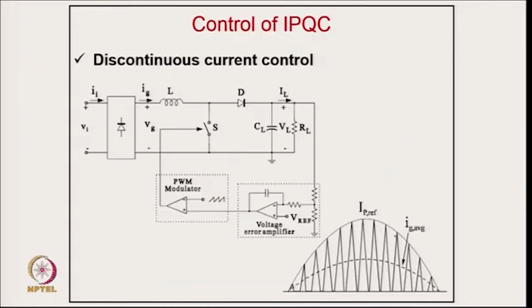The peak current is much higher, because this is the current you will get, not the average current. Typically in an inductor, the peak current will sometimes be even more than double in this case, because you are missing some period here. So, we make a design, of course, for the boundary condition, and then we select the inductor lower than that. It means the inductor size is reasonably reduced in this case.